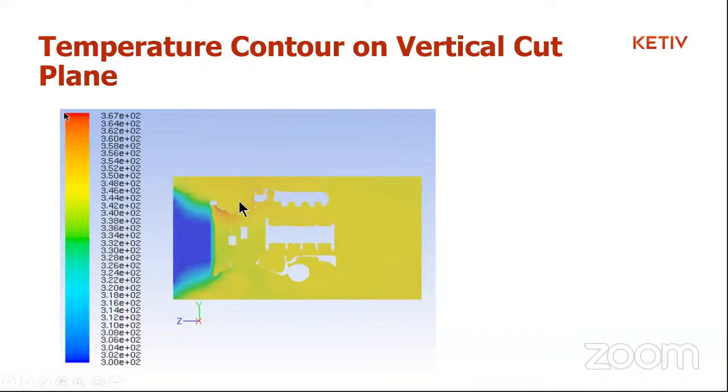So when the fan is not designed properly, or the shroud is not as such that you can get uniform velocity, then you will see higher temperatures in those regions. So depending on these metrics that you see in the contour planes, you can tell where the problem lies and how to fix it, right? So that could be another way to do it.